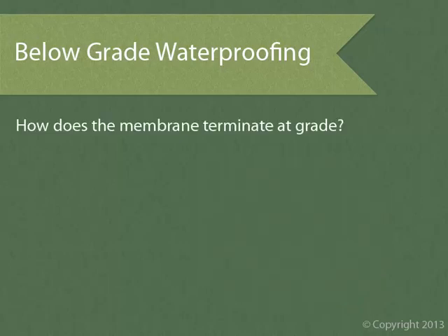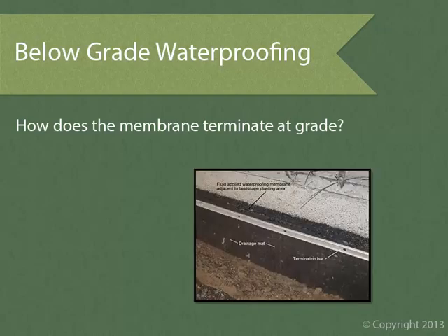Below-grade membranes are designed to be underground and out of sight. So as a result, manufacturers really don't put any consideration into making them look pretty. Although 99.9% of the membrane is out of sight, we do need to run it up 6 inches or so above grade and lap it behind the facade so water properly sheds down over it. As you can see in this photo, a membrane and drainage mat need to be concealed from view at the perimeter base of the building.